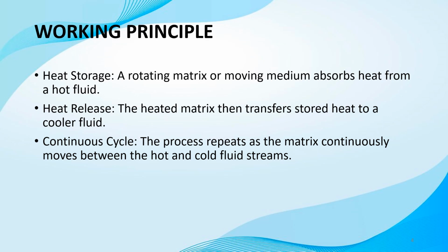Working principles of dynamic regenerators. Heat storage: a rotating matrix or moving medium absorbs heat from a hot fluid, which is stored temporarily. Heat release: the heated matrix then transfers the temporarily stored heat, which was absorbed from the hot fluid, into a cooler fluid.